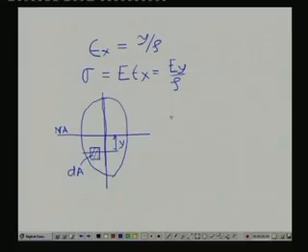So, we know the small force, and this force we are considering to be dN, is nothing but sigma into dA. If it is sigma into dA, then what is the total normal force acting onto the entire cross section?